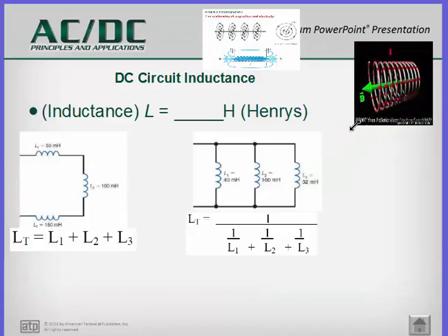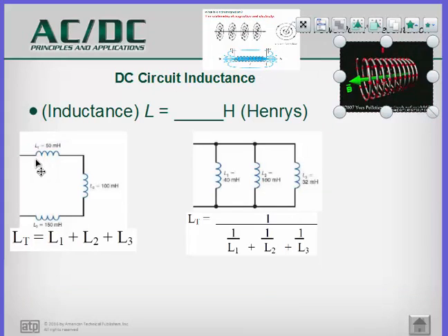We're also going to talk about how inductors in series add up. They add up just like resistance in series, or if we have inductors in parallel, the inductance adds up just like the reciprocal formula that we used for resistors in parallel.